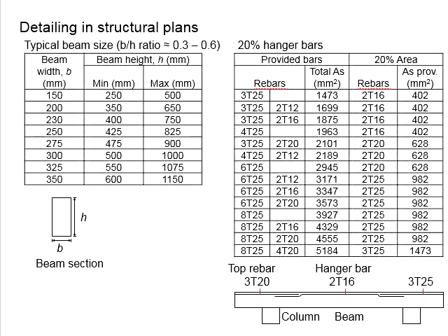Now what happens here is, you will know that these regions might not be subjected to a high degree of tension force, and are likely to undergo compression only. At the midspan, the tension will be at the bottom of the beam, and compression on top of the beam. That means there will be a significant change in the stress in the concrete, from tension to neutral, and then to compression, and then to neutral, and then to tension.